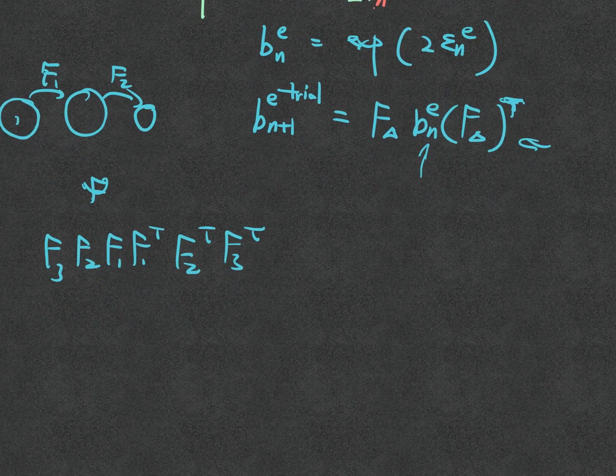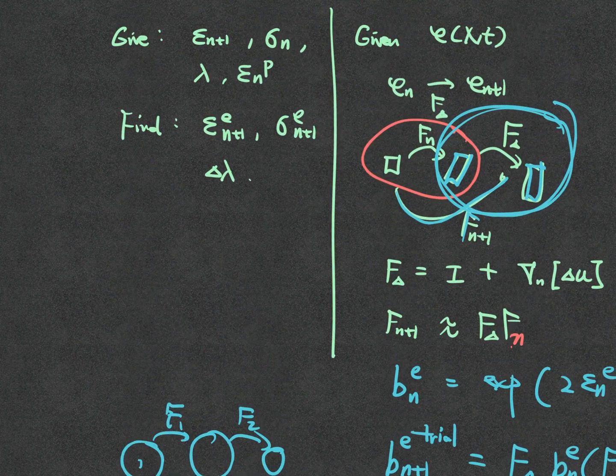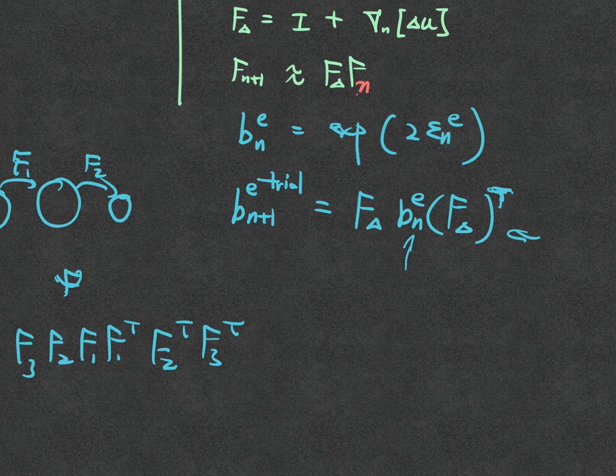Okay, so now, long story short, let me talk about the next step. What is the next step? I apply the exponential mapping, right? Then I want to write something in small deformation. So I want to convert these expressions into epsilon_{n+1}^e trial. The corresponding thing here is the logarithmic mapping.